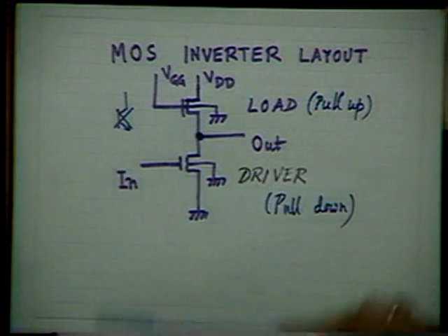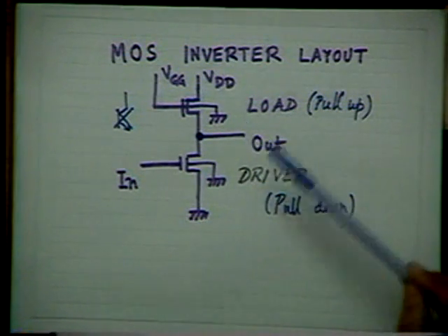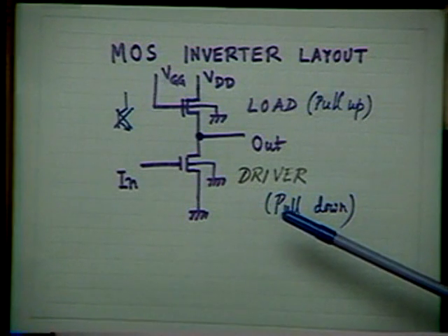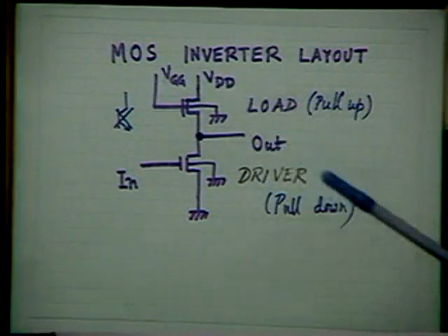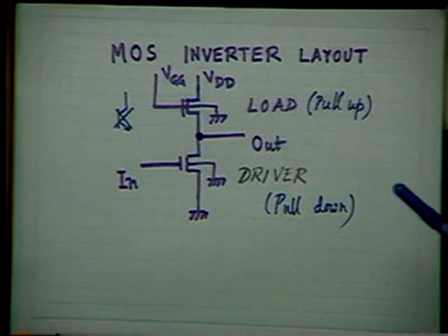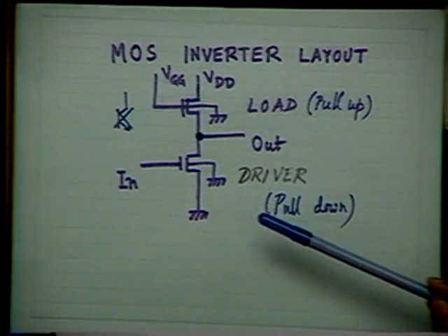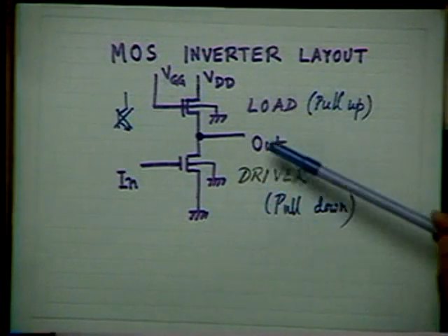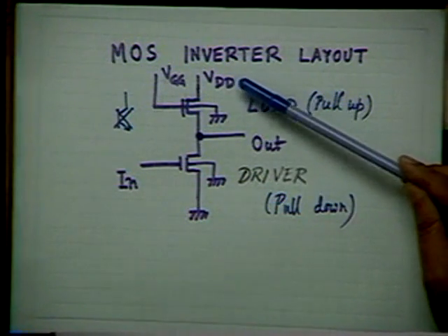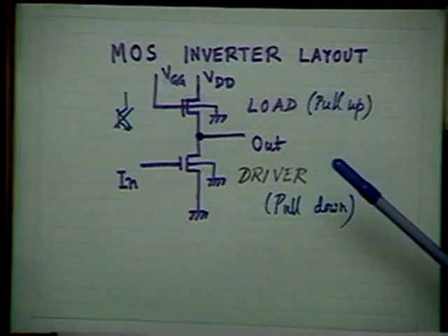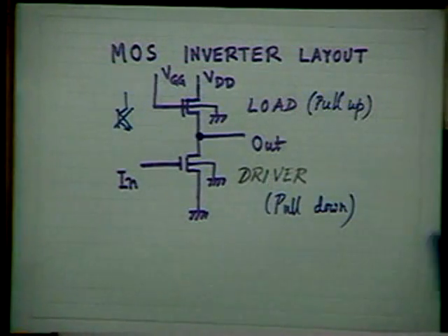So when a switch is on and off, the output voltage also switches from a very low positive voltage to near 5 volt, the VDD. It may be 5 volt. So the output swing is from a very low positive voltage to a very high one, up to the power supply positive voltage. And this output is suitable for switching another such inverter which is connected to this output. You know that this is nothing but one inverter of a very big circuit. It is a building block.